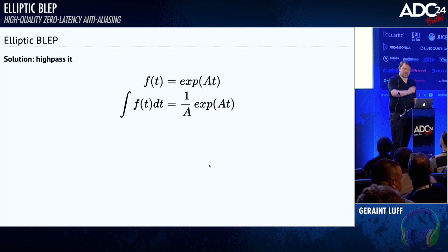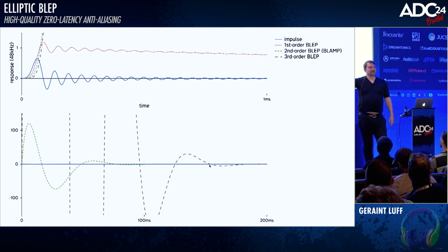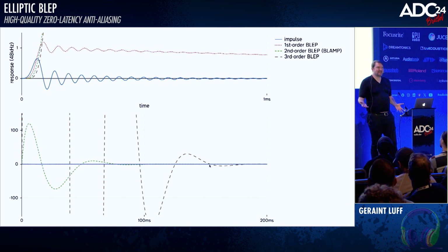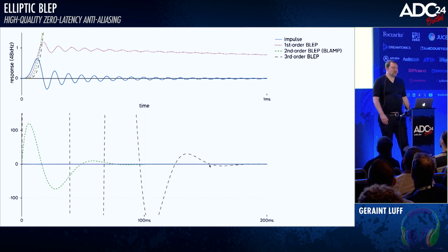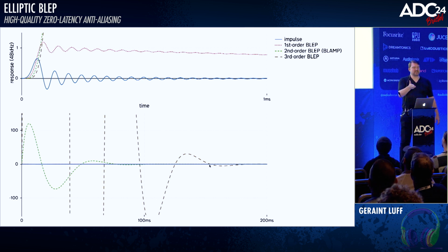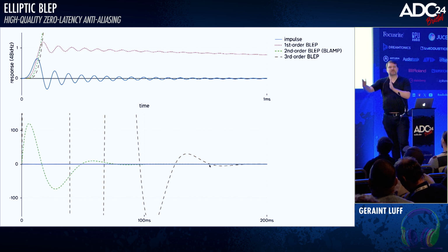Well, it's not infinity, because as you can see from this zoomed out one, zoomed out in time and frequency, they do in fact oscillate. They just oscillate very slowly. But we high-passed it around 20 hertz, so it's not insane that the second order one is settling down around 50 milliseconds or so. That kind of scans. But this works. If you make sure that the filter you're integrating has a lot of zeros at 0, then you can integrate it to get these continuous time, arbitrarily addressable filters.